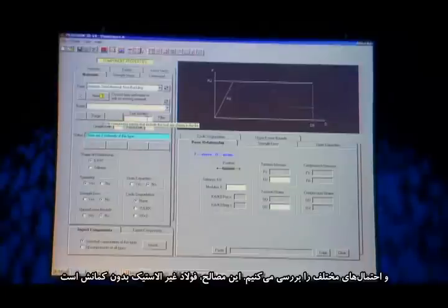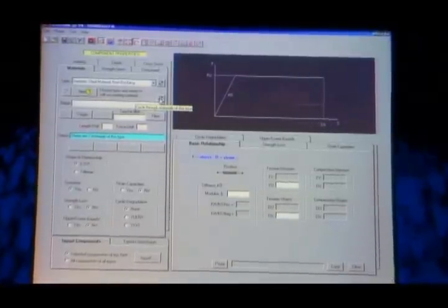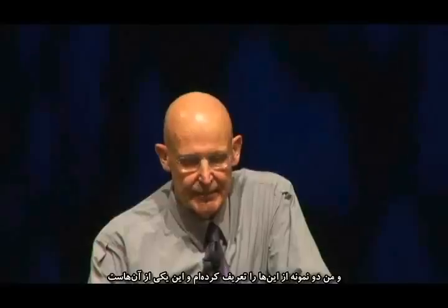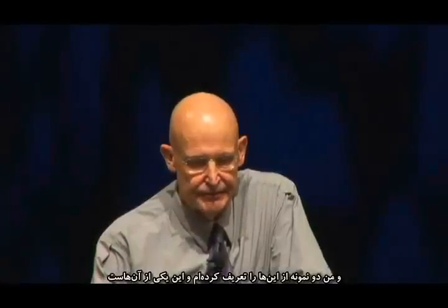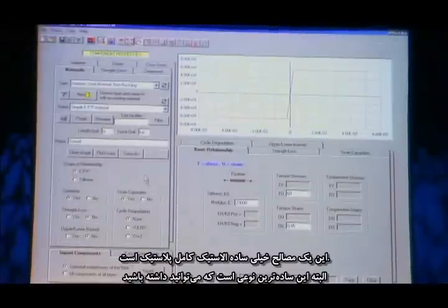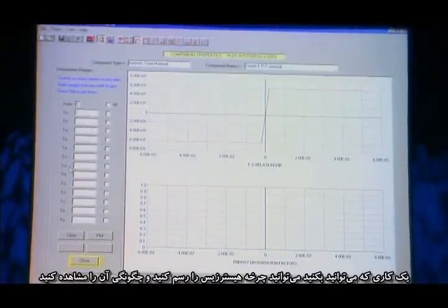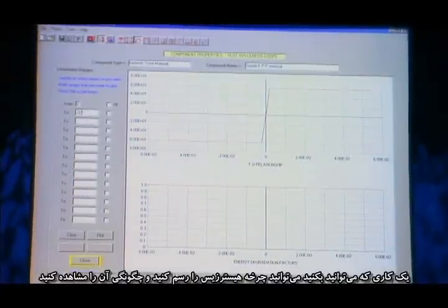What I'm going to do is go to materials here and just look at some possibilities. This is an inelastic steel material without any buckling, and I've set up 2 of these. This is one of them. This is a very simple, elastic, perfectly plastic material, but this is as simple as you can get. And one of the things you can do in Perform is plot hysteresis loops here and have a look and see what they look like.